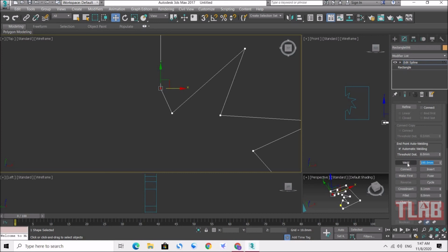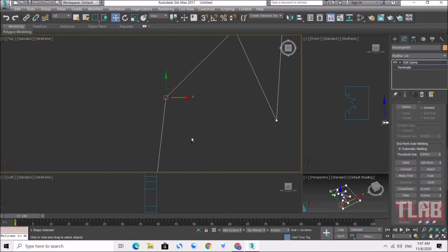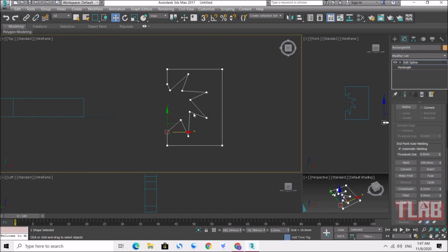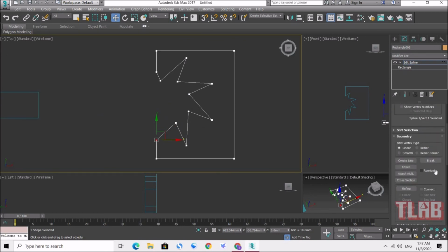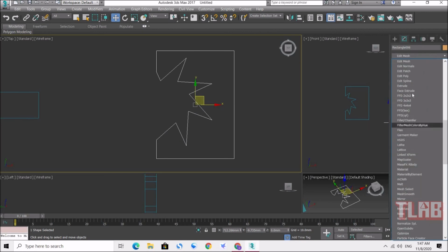So just click Weld. After that, click already. Then you double check. Has it become 1 already or not? You see? Okay, it's joined already. So this one also select. Weld again. Okay, that's all. Okay, so now you can double check. You see? Okay, so if you complete all this, now you can deselect the tag, go to modify list,